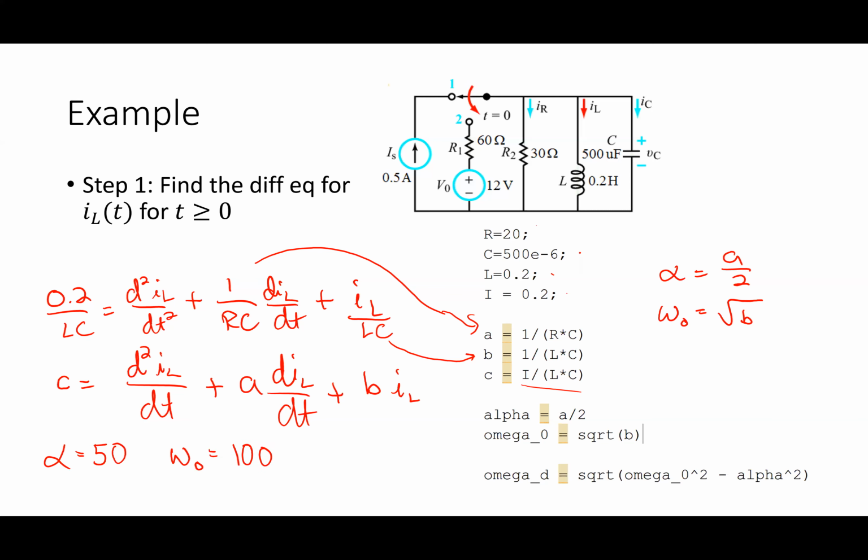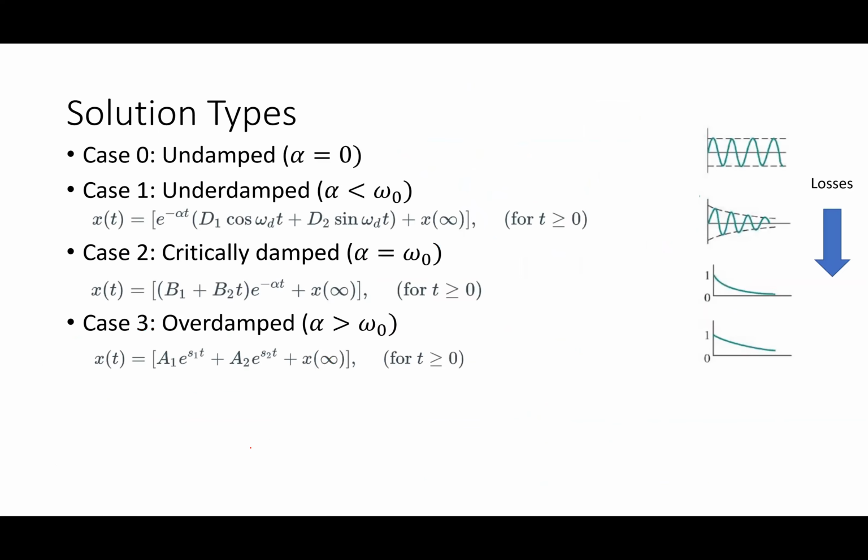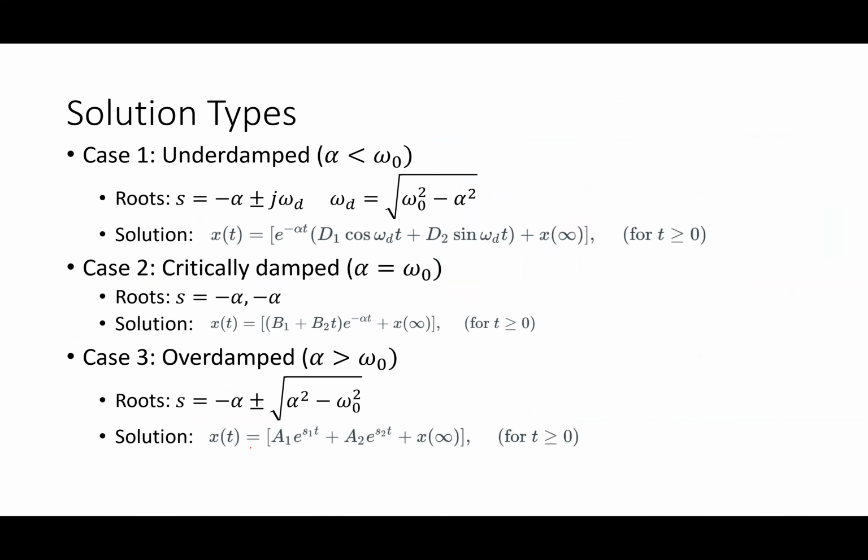So what do I do now? My next step. Use underdamped. Use underdamped. And why is that? Alpha is smaller than omega naught. Omega naught is bigger than alpha. Yeah, alpha is smaller than omega naught. So that means that I've got this underdamped response over here. Oh, my mouse pointer disappeared. Yeah, alpha is less than omega naught. And so what that tells me is I've got this response right there, right? That's the equation I'm going to use. I get these decaying oscillations.